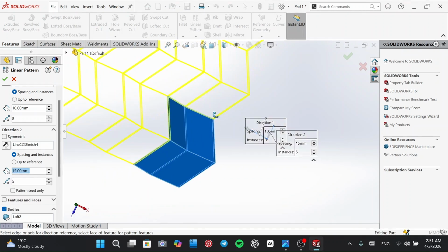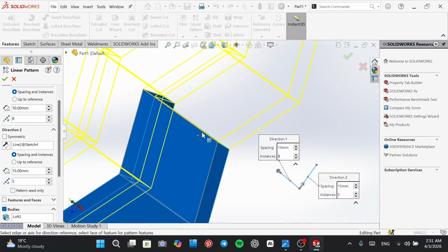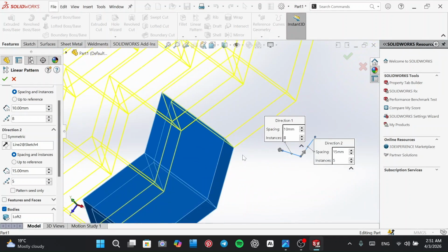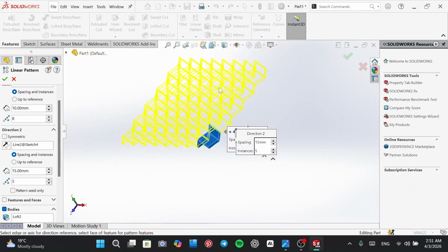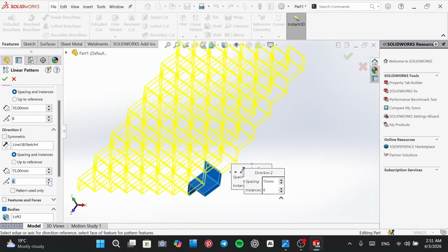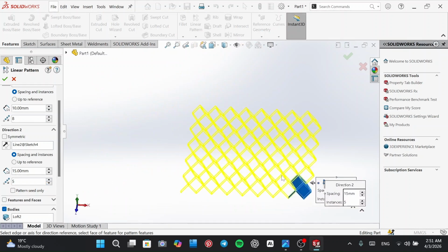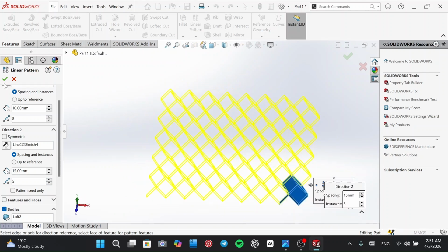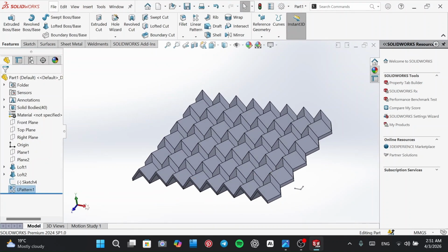At each 15, there will be a new cell. So there is no interference between the unit cells. And no errors. We can choose how many unit cells we have. Okay, set it 5, or as you like. Okay, now set OK. This is the unit cell we have.